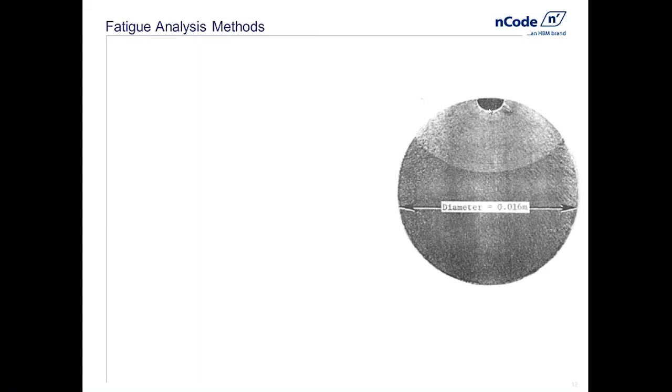We can see then that this crack grew going through this middle bit. If you look really carefully, you can actually see these concentric rings, like growth rings on a tree. Just like a tree grows every year, and if we cut down the tree and take a good look, we can see how old it is and what years were favorable towards tree growth that year. Likewise, we can see here, this is essentially charting out how the crack has grown.